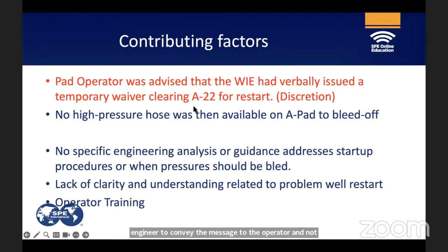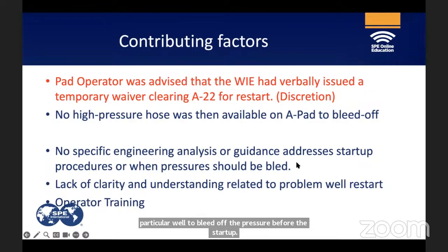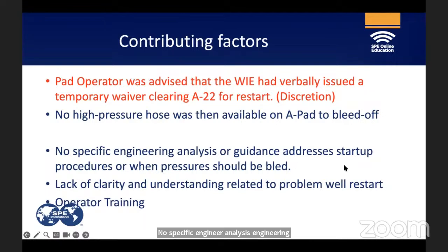No high pressure hose was available on the pad for that particular well to bleed off the pressure before the startup. No specific engineering analysis or guidance addressed the startup procedure or when the pressure should be bled. There was no clear procedure or written guidelines for the wellhead operator to perform the task.